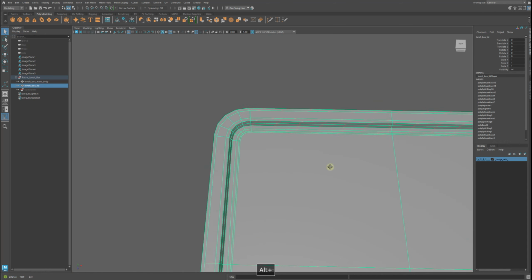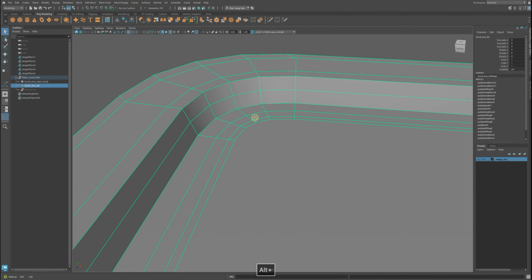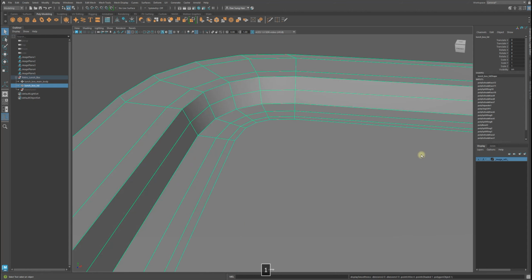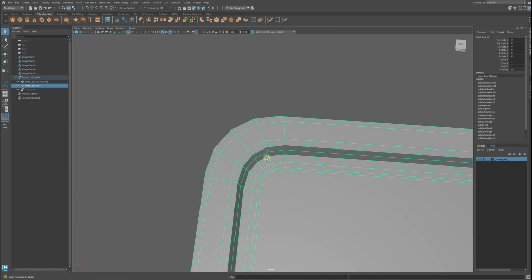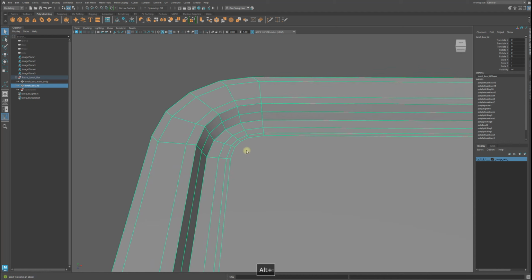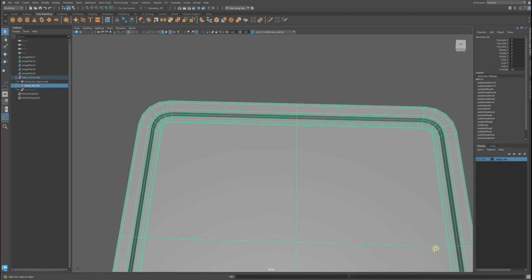What I'm gonna do is, again, you could say this is kind of like rule of 3, because the rule of 3 also matters for UV mapping, so that you avoid this stretching right here. This is gonna cause some potential issues with UV mapping projections, like a skin. You want the skin to be nicely, evenly laid out, like you're grafting skin or something like that. Okay, so we have that. I'm gonna start cleaning things up.